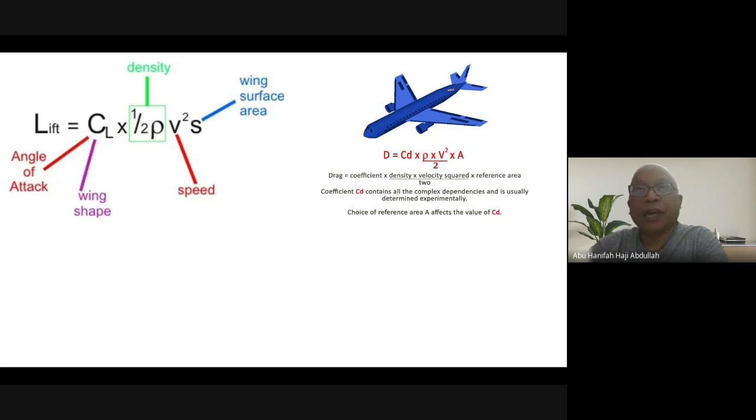They flew at very high altitude where the density is low, with the same flap setting as flying at sea level. They ran over the runway, could not even achieve V2, tried to rotate, and usually crashed beyond the runway. Such cases occurred in countries with high-altitude airports. Also, not achieving enough speed and velocity will cause a crash.